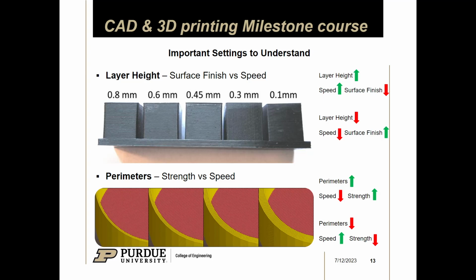You can have variable layer height, if that's what you're talking about, but mostly it's on a per layer basis thing. But yeah, so you see on the top left, it has a layer height of 0.8 millimeters. So you can see on this presentation, even if you're far away from the screen, you can see the different layer lines, right?